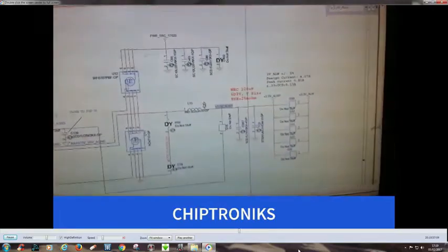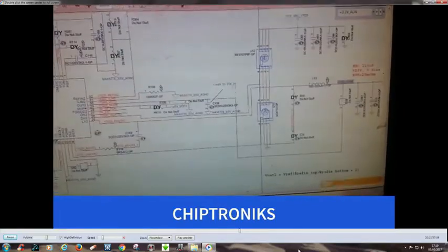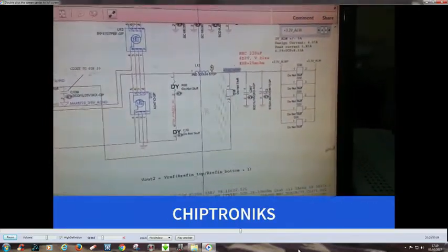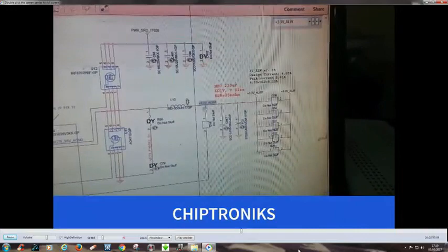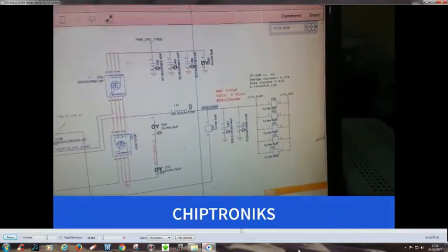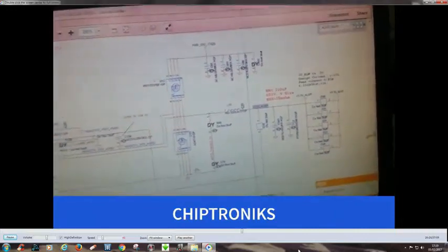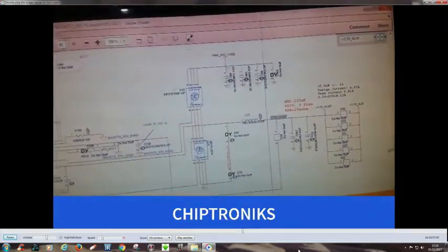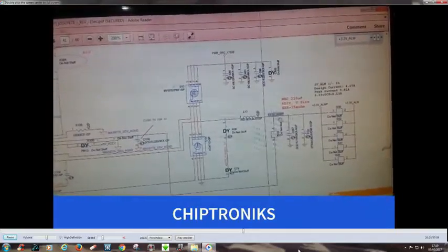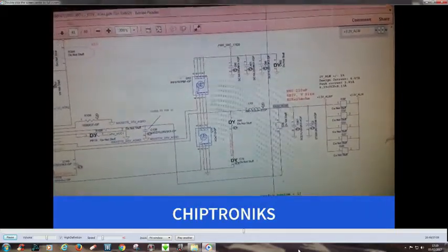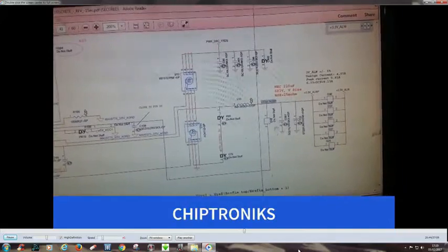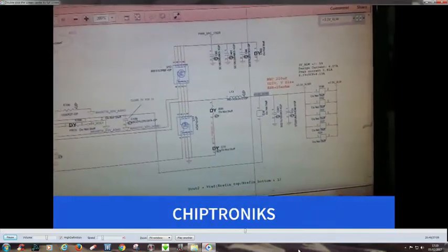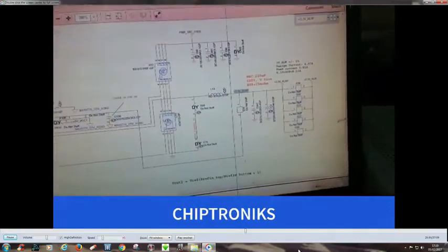Yeah, so you can see this is coming out from the 3 volt 5 volt regulator IC, and you can see this is 3.3 always on. This is coming after switching these two MOSFETs. After these two MOSFETs switch, this PWR SRC, this 20 volt, is getting converted into 3.3 volt. So if this is not generated, then you need to check these capacitors, you need to check these coils, and you have to check these two MOSFETs.